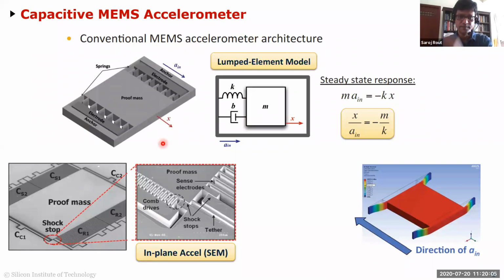And this is a typical accelerometer. The company I consult for on the gyroscope, they actually make the accelerometer as well, a different kind of accelerometer, but kind of similar. So this is actually a MEMS device. As you can see, it's actually a mechanical system, very small. This is also the size of a rice grain. And you have all these little capacitor plates. So when you start accelerating in one direction, because you have a mass, and the mass has a force because of the acceleration, because it looks like this mass spring, it starts moving in one direction, and that changes the capacitance, and you basically measure the capacitance and measure the acceleration.